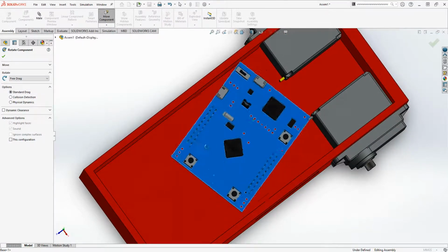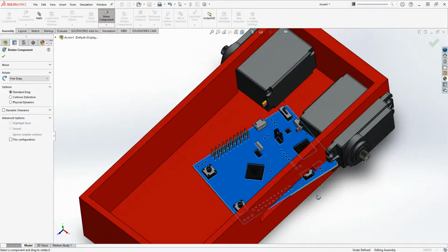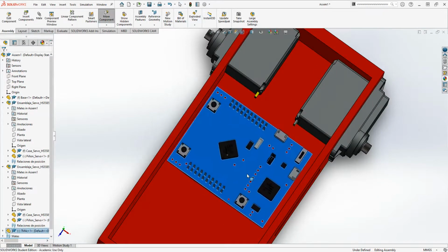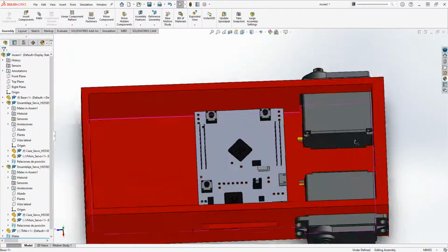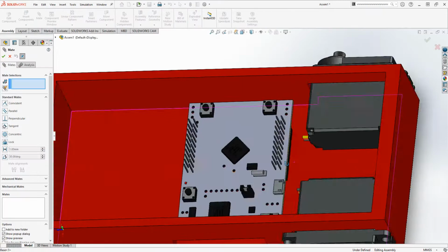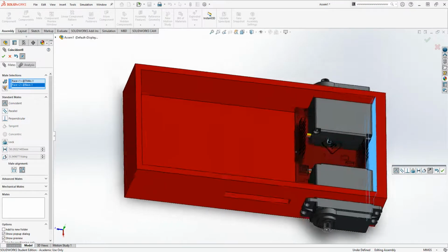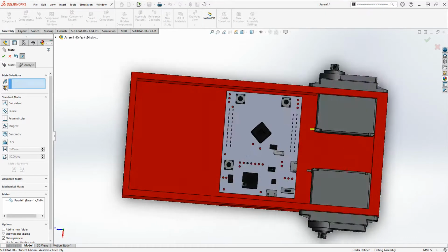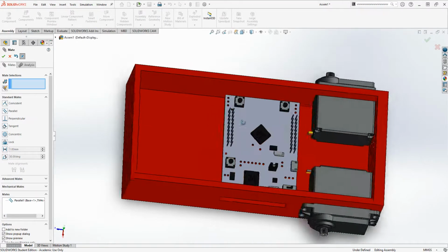All these are little things you have to think about when building your robot. Is there enough room? Now, you might do this with calipers. You have to measure all your parts and pieces and see how much space they take up. In designing this chassis, I wanted to make sure that everything I was making could fit within it. That means I need to know the dimensions of this microcontroller. How do these motors fit in? How much room do I have? All of these have to go in line. You have to think of total length and slight additional spacing. It's really a trial and error process sometimes. So maybe even just placing these components in a basic pre-testing assembly and then checking measurements and how the spacing looks is a great idea.